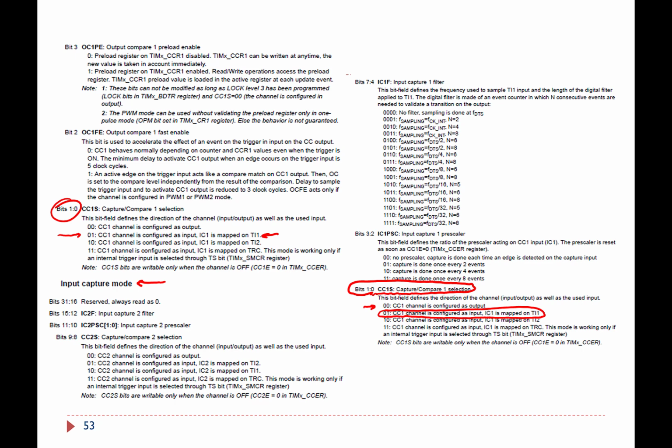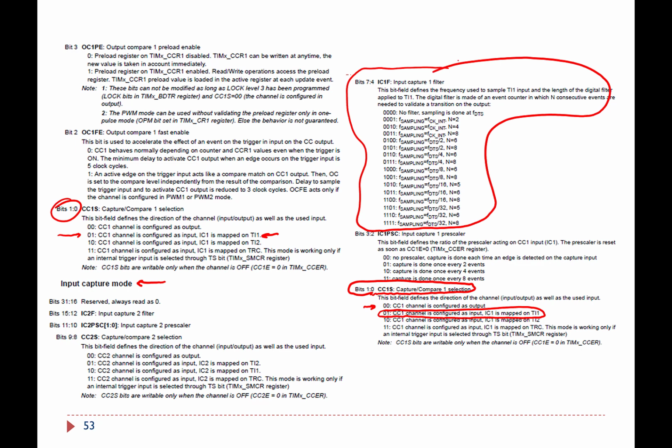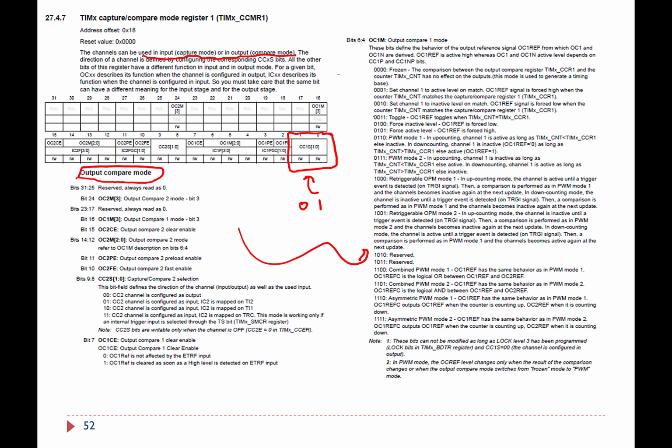Again, what makes sense there is here are the filtering parts that I was talking about. Now we didn't change that, right? We didn't put anything there. So we told it to filter, but we didn't tell it to actually filter anything, because we let those bits be zeros there. If we change those, then we would have had that filtering actually taking place. Anyways, you can see what's going on there, and that's just finalizing this and showing it more carefully with that input capture for the capture compare mode register.